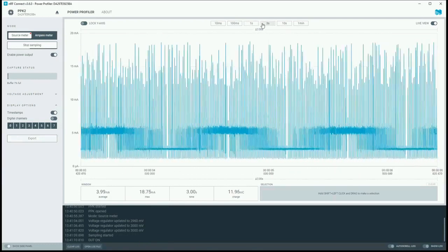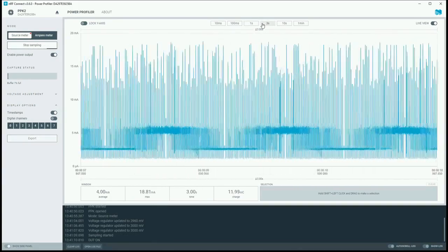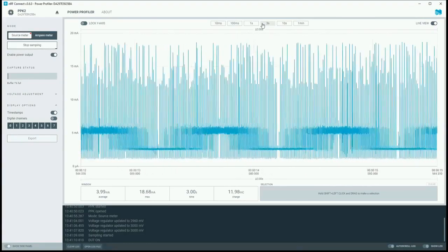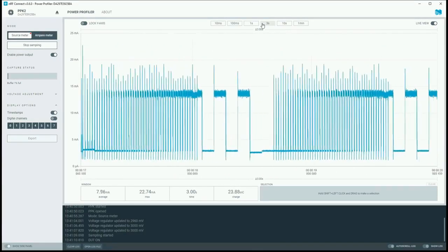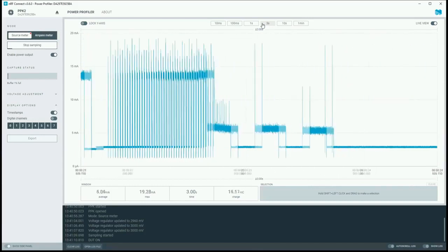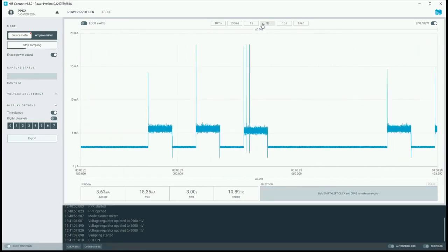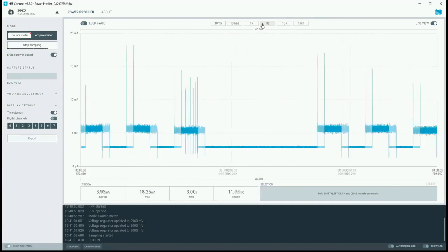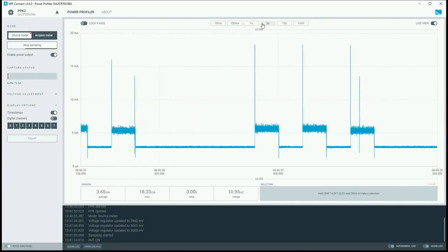So in this example, it's a PWM driver example from the SDK, which will change between some demos when I press button 1 and 2. So by pressing a button, we can see from the current consumption that it's changed to a new demo. And for this example, for instance, it's toggling an LED 3 times and pausing, and then toggling them again 3 times. And this is clearly visible from just looking at the power consumption.